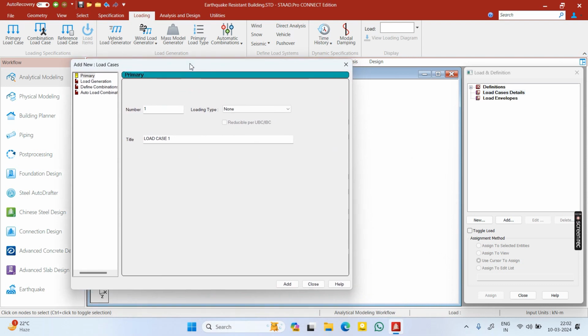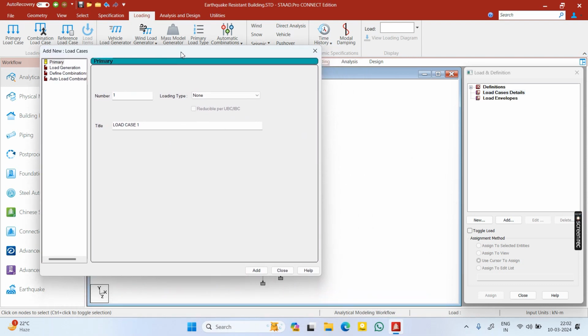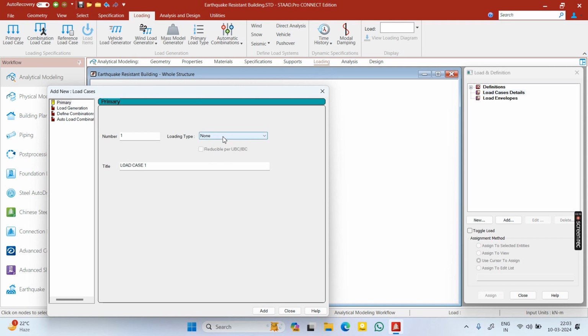So in this lecture we are taking two load cases. First is our dead load, in which we put the self weight, and just build the building and apply the earthquake. How will the building respond when the earthquake is applied, that we want to see. Once the building is built, nobody is living in it yet. If it is a residential building, we have not given any flats to anyone, so no dead load or live load will be applied. There is only dead load, meaning beams, columns, slabs, and only the earthquake comes at that time.